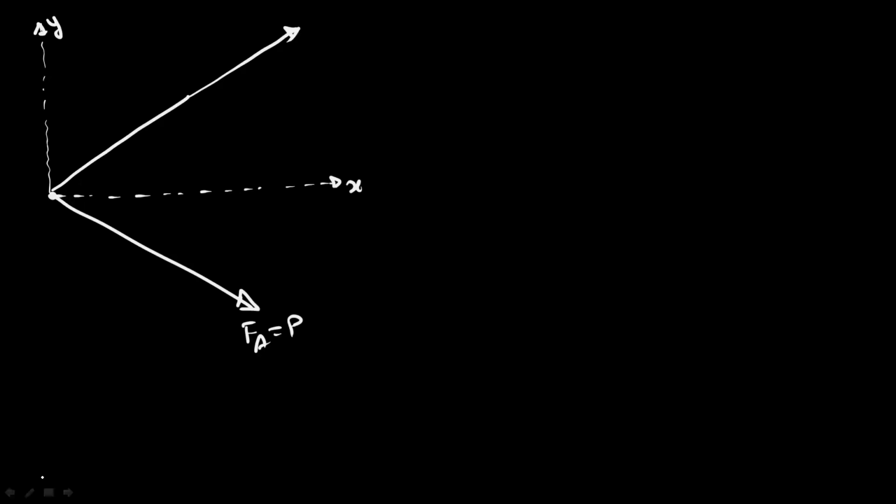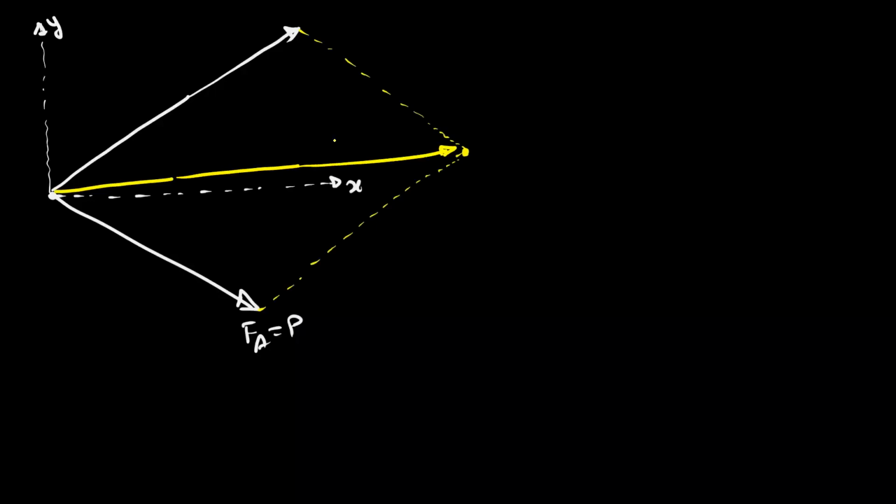So if you construct the parallelogram with proper dimensions, then the resultant will be just above the x-axis, like this. So this is the resultant. And this total angle with respect to force P is theta, which is equal to 36 degree. In the diagram, 30 degrees is given for the force P with respect to the x-axis.